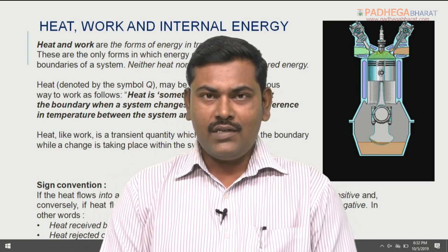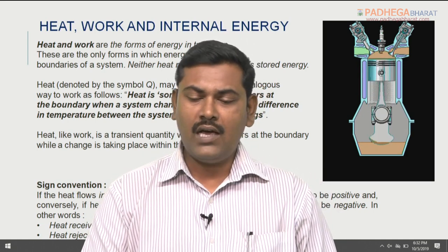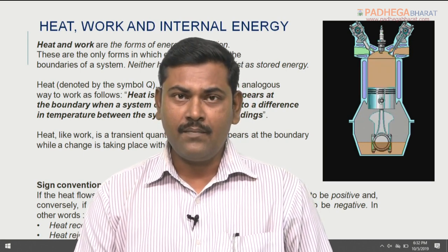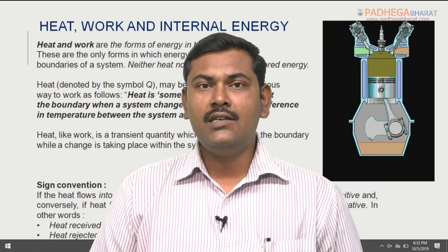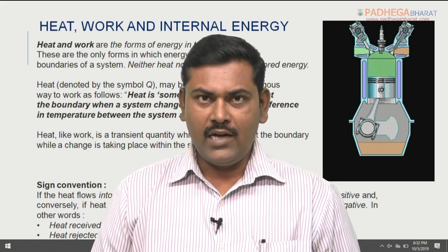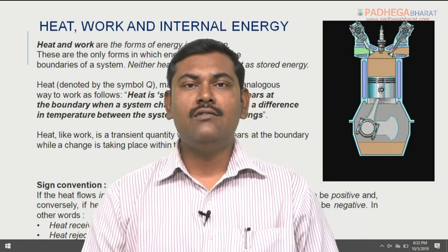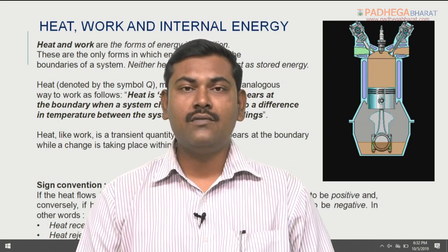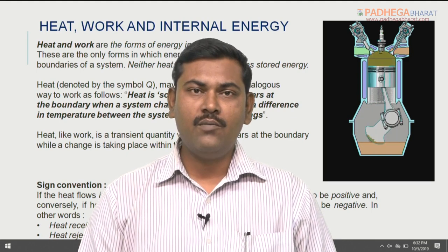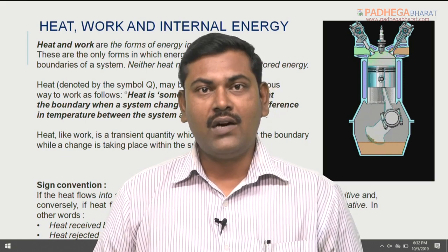But have you seen the working? Have you seen the effects, or the conversion of heat into mechanical work? Yes, definitely. We have converted chemical energy of fuel by burning it. Burning is nothing but an exothermic reaction. So through this exothermic reaction we have converted heat energy into mechanical work, and that's how we develop the reciprocating motion, and finally that reciprocating motion is converted into circular motion, that is, the rotary motion of our wheels.